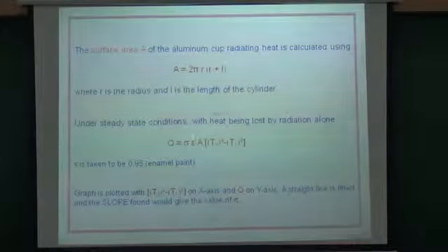The positive value and the negative value can be obtained by the DC differential amplifier. We find out the corrected value, which is the positive value minus the negative value divided by 2. We convert it into a difference of temperature by dividing this by 40 microvolt per degree Kelvin.